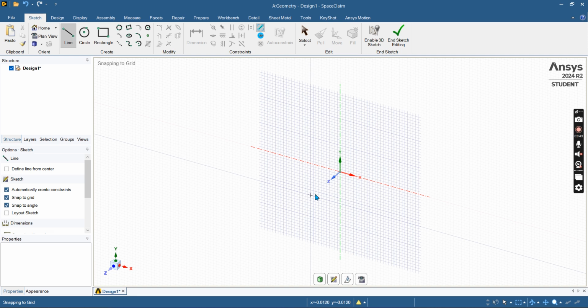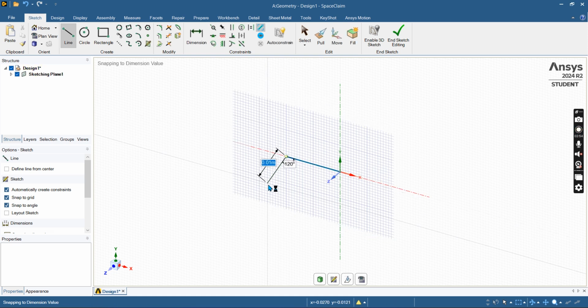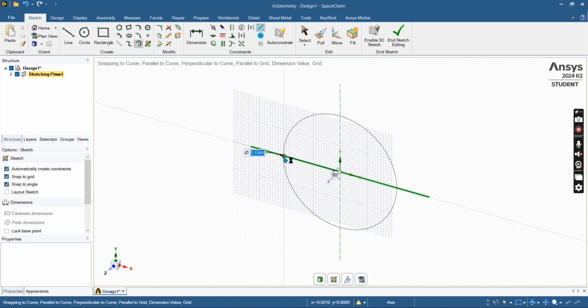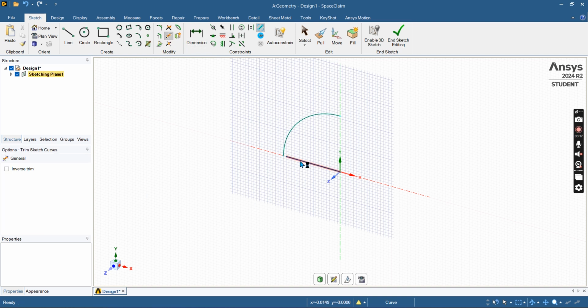Now I will choose the bend profile. So choose this point and this point. I want a 0.02 meter bend, so I have chosen this point. Now escape to skip this operation. Now we will make a bend section out of this radius. So go sweep arc and choose this point and this point. It will act as a radius of this new circle. Now I don't need this line, so I have to delete this. So trim the part with this operation and the line will be gone.